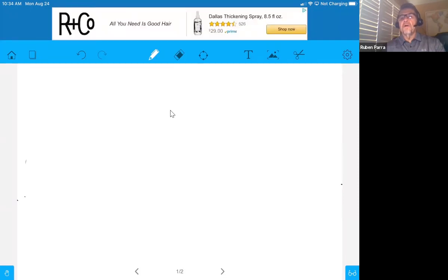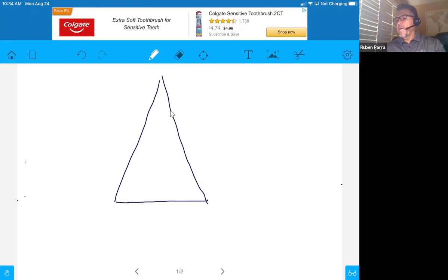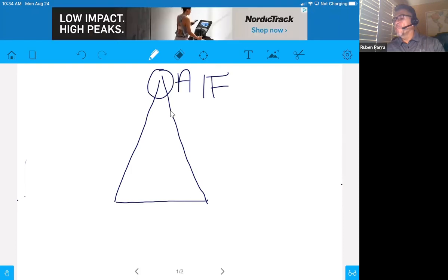A lot of things have changed as far as engine performance, but what I want to talk about is something called the engine performance triangle. If we draw a triangle like so, we notice we have three equal sides, and it doesn't matter which side you pick for which component, but for each of these sides, you're going to have something. First of all, we'll start over here, and we'll call this corner the air-fuel corner. One of the requirements is going to be the air and fuel, okay? And when we talk about air and fuel, we talk about something called the air-fuel ratio, okay? That is what part to what part is required.